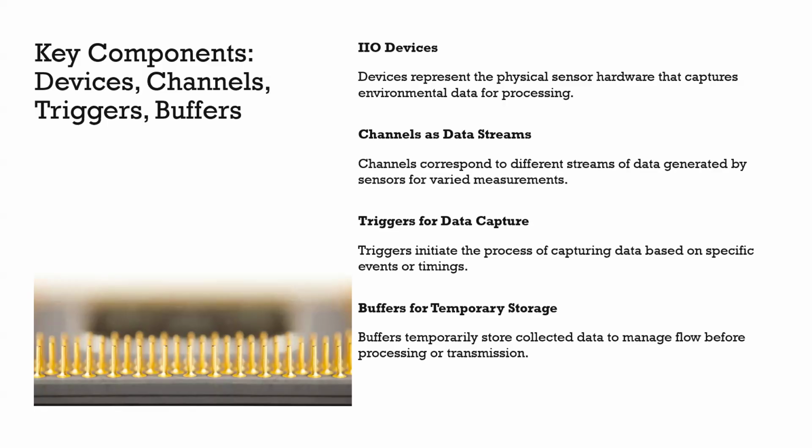It basically handles the data in a circular buffer. So it keeps on filling the data into the circular buffer. If one buffer is filled, it will just pass to another one, and it keeps on filling. And suppose the user is not reading, even in that case, what will happen? If the circular buffer is filled, it will keep on overriding the previous data. But in general, if the user application keeps on reading, as soon as it reads the data from the buffer, it clears the data.